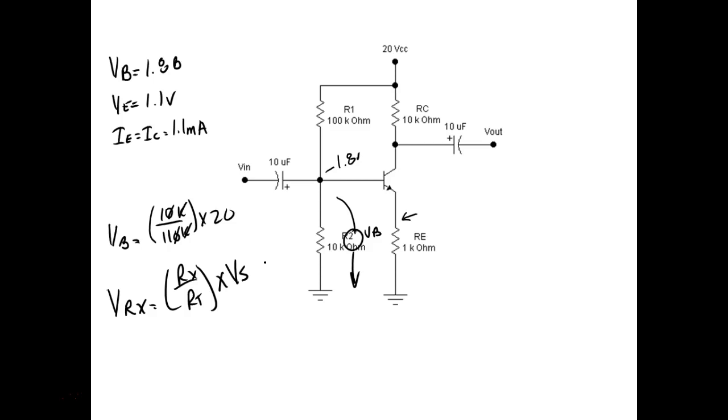And I say, okay, what would happen to the voltage drop across the 10K if I lowered the voltage to 8 volts? What would they do? They would recalculate the whole circuit, when the ratio that 10K drops will always be 1/11 of the applied voltage, period. Always. So if you knew the ratio, then you could have recalculated the circuit just like that, right?